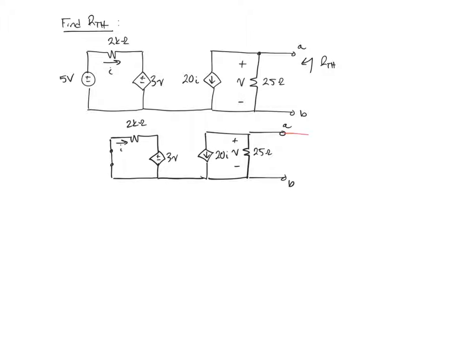So again, we're going to attach an independent source on the output. I usually like to use current sources just because the voltage that I find being dropped across that current source is going to also be the same as the value of the Thevenin equivalent resistance, because it will be V over 1. Noting here that our value V, which is the dependent variable, just equals V sub SD directly because they're in parallel with one another.